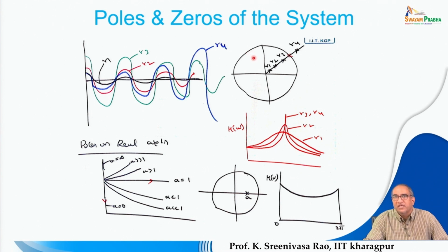Suppose we want to produce E, where the first formant will be in a very low range and the second formant in a very high range. Then accordingly we will set the bandwidths also. So, based on our interest we can set these poles at different locations on the z-plane, and with the collective effect of 3 or 4 pairs of complex conjugate roots we can synthesize the sound of our desired interest.